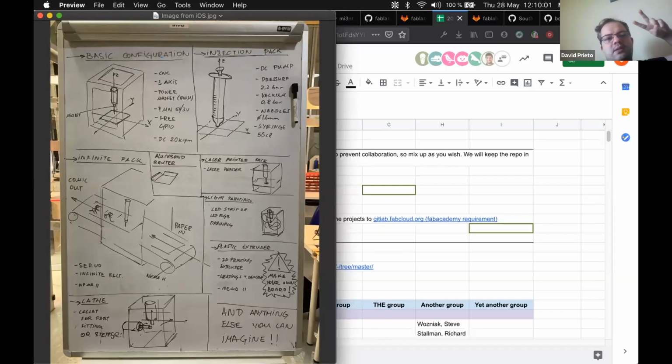So in this case, to be clear, the solution about coordination between X and Y and Z is that the ESP32 knows it all and just sends the signal to each stepper driver to move, and that's it.